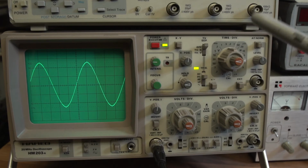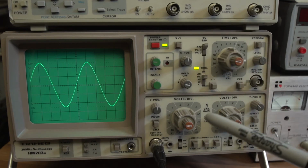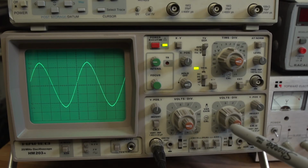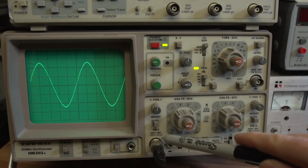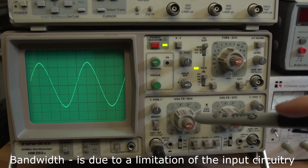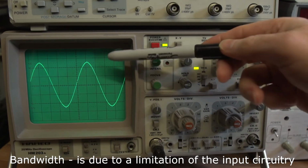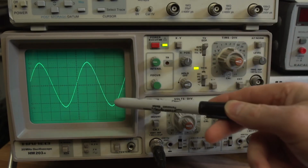But what happens if we start to actually wind up the input frequency higher than 100 kilohertz? What if we take it to a few megahertz, 5 megahertz, 10 megahertz, and so on? Well, with oscilloscopes of this age, and this scope's probably about 20 years old, I think, thereabouts, there is a limitation to the bandwidth of the input amplifier circuitry within the scope itself. And as you go higher in frequency, you will start to see an attenuation of the amplitude. In other words, the calibration is not correct anymore.